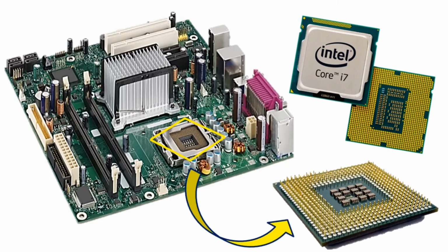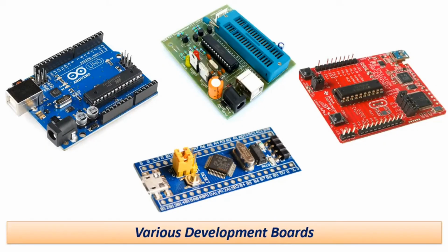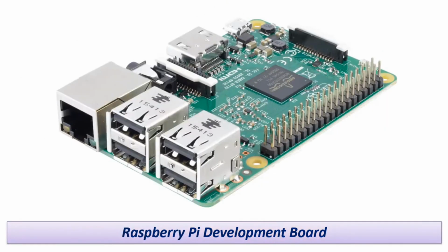Instead of the modular structure of our computers, in the microcontrollers we use in the development boards that are widely used today, all the necessary units such as the Central Processing Unit, or CPU, memory, or RAM, and hard disk are gathered in a single integration. Microcontroller ICs are programmable. In this way, only one job will be done. These ICs are used in relatively simpler applications. The written program is saved in the microcontroller program memory and runs continuously when the IC is energized. Companies such as Atmel, PIC, Texas Instruments produce very different kinds of microcontroller ICs.